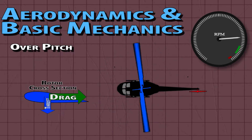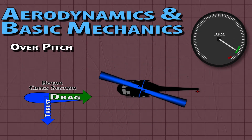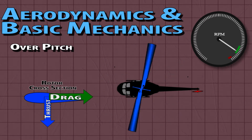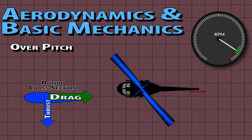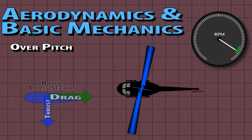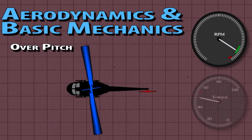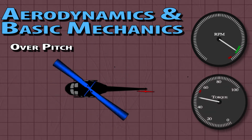Remove the drag and wait for the RPM to rise. Take care when adding pitch to not do so faster than your aircraft can handle. The lift equation has a squared component, i.e. the velocity of the air has an exponential relationship with lift. This means even a few % decrease in rotor RPM can lead to a large decrease in lift.